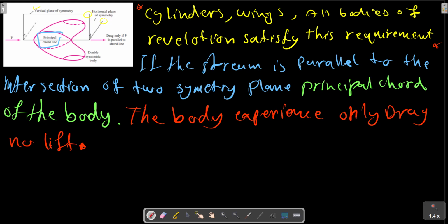This type of degenerate one-force drag data is what is most commonly reported in the literature. But if the free stream is not parallel to the chord line, the body will have an unsymmetric orientation and all three forces and three moments can arise in principle.